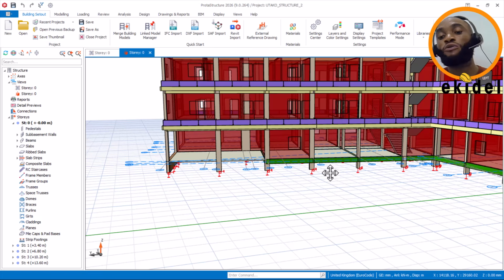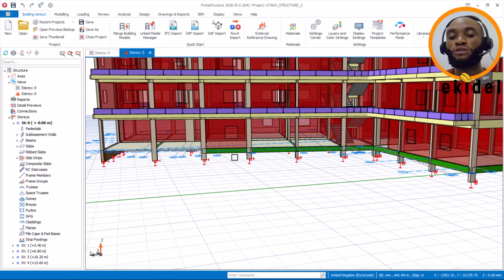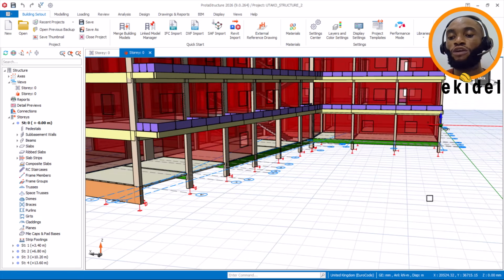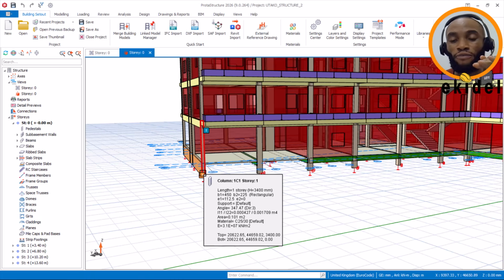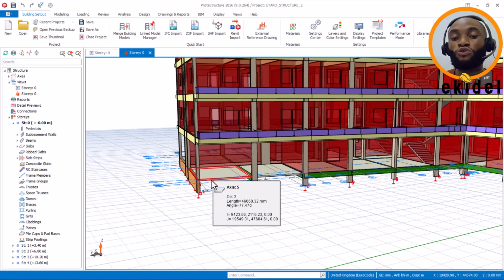We are going to achieve that by creating a support level, because these other columns around all this side here, around this whole area here, remain the same. Okay, only the basement floor is going down by 2.3 meters from the ground level. That's from story zero down. So with that, we are now going to create a support level.